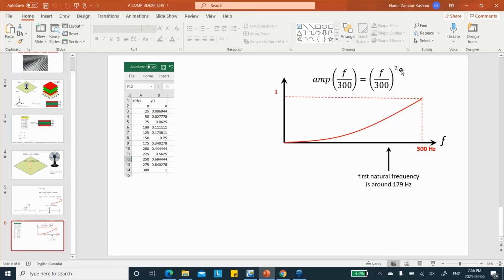Now, what I need to do is, for f squared, create an amplitude which at frequency 0, of course, is 0, and the range that we're going to look at is between 0 and 300 hertz. If we look at 0 and 300 hertz, then the amplitude function that we're going to define is going to be something like this. I have to give this curve to 3D Experience.